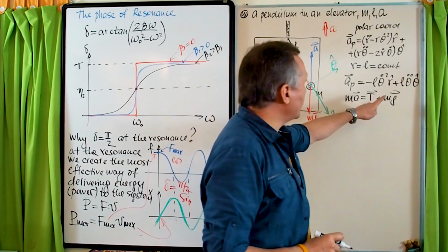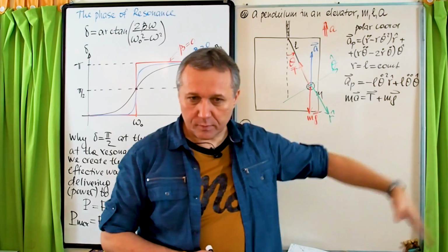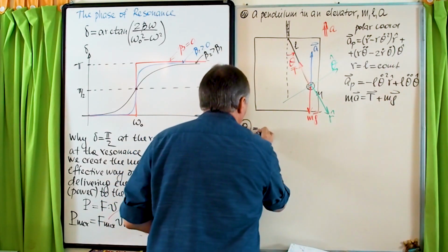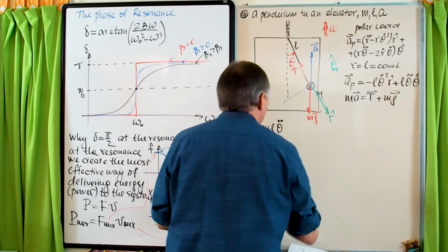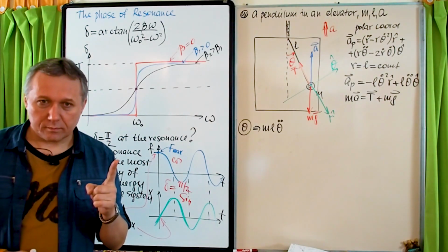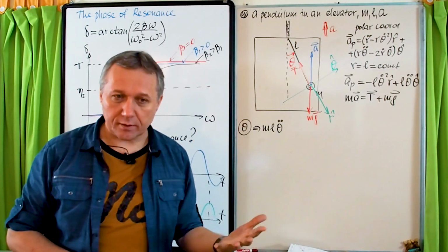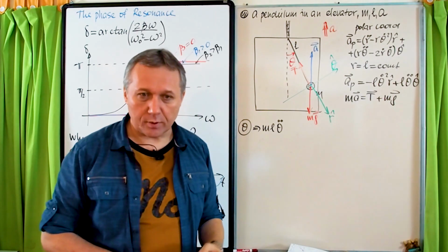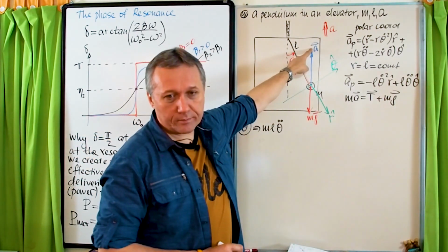So first, mass times acceleration. Acceleration in the theta direction because of the motion of the system is ml theta double dot. All right. But at the same time, we know there is a motion of the whole system up. So there is an additional acceleration, so we need to add it to the acceleration side. So it's mass times the theta component of this acceleration.